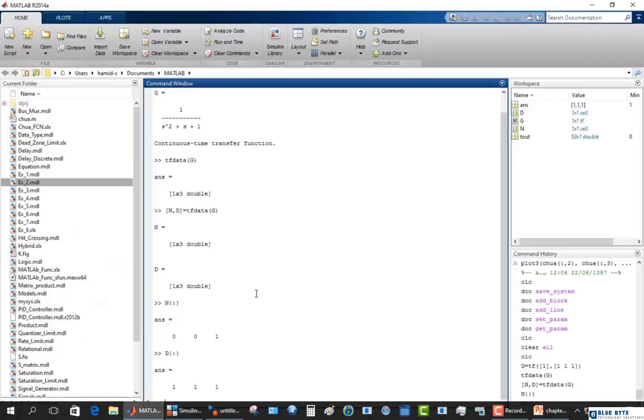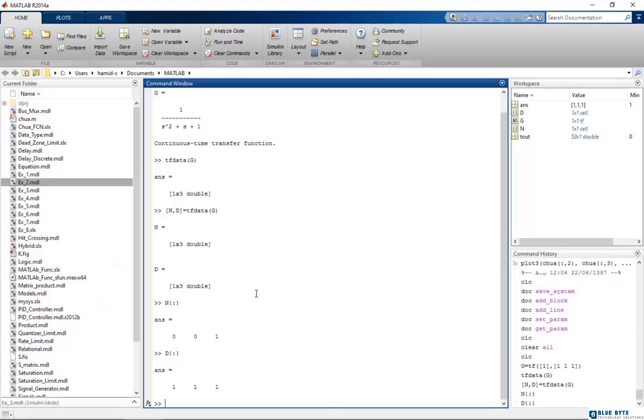Okay, now I'm going to explain system simulation by using codes, that is, how we can make a Simulink space by code. MATLAB enables the user to create a Simulink model by MATLAB codes, without using blocks and modeling. In doing so, we use the new_system code.